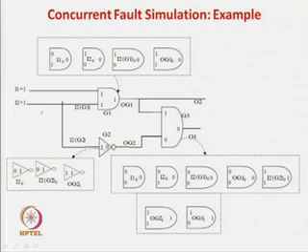Okay. You can also think that this is a kind of parallel fault simulation, where you maintain an array, but here the array size is unlimited. We are not going for any kind of computer architecture oriented algorithm. So, if some 100 faults affect a gate, you will have some 100 gates in that bubble. Here we are not using the architecture kind of a thing.